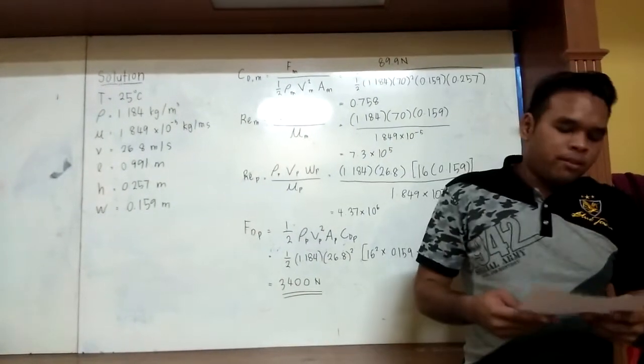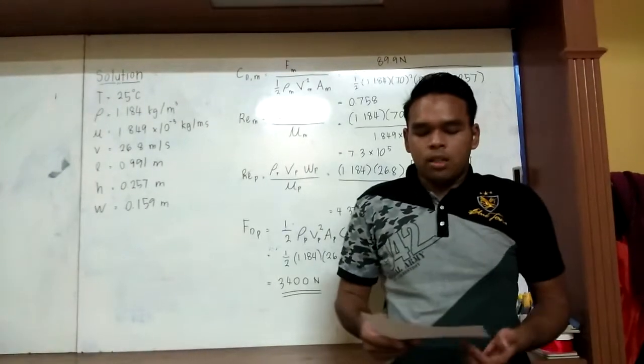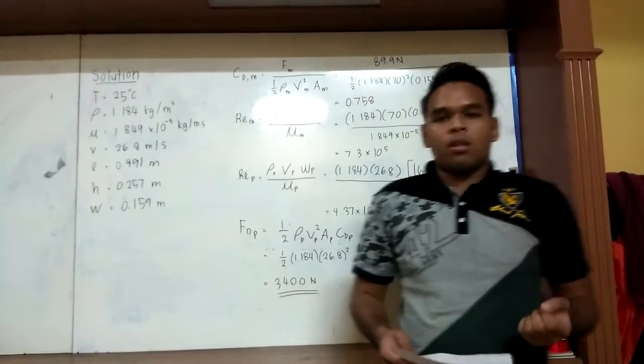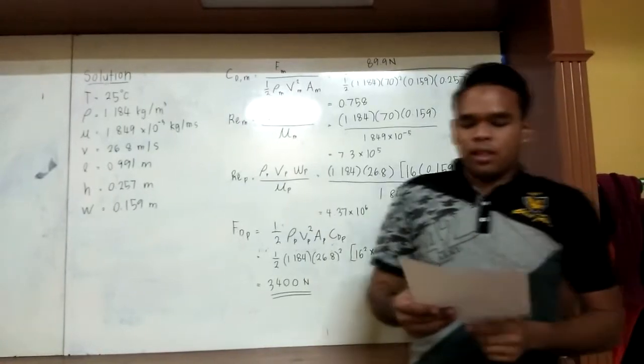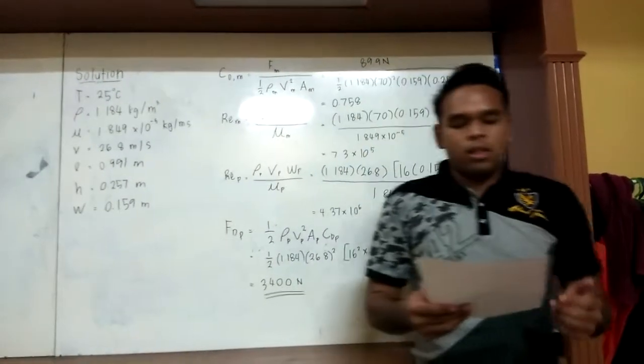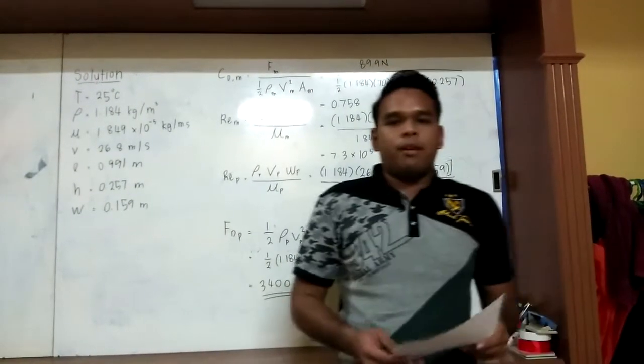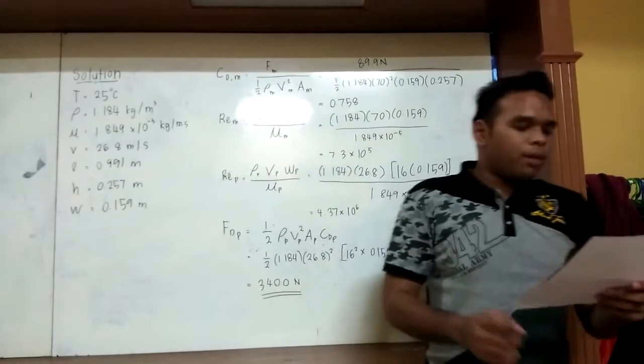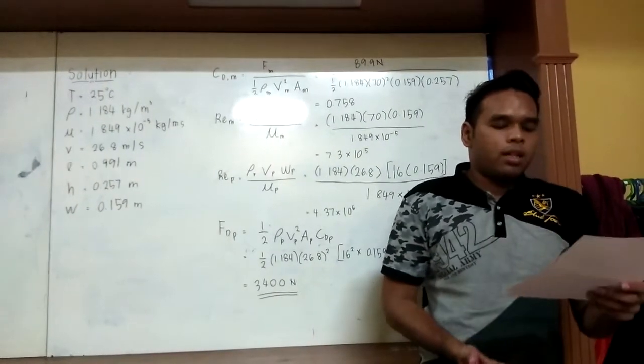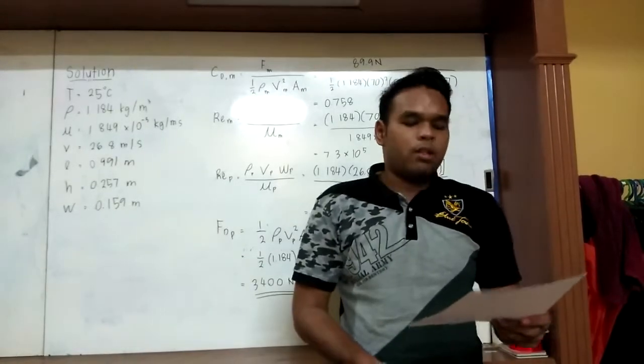The method of repeating variables is used to generate the non-dimensional parameters. It is a step-by-step procedure, or recipe, for obtaining non-dimensional parameters. It has 6 steps. The first step is to list the parameters in the problem and count their total number, n.